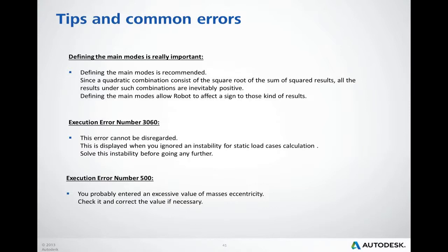Sometimes error 500 may appear. It's related to excessive value of mass eccentricities. In such case, it's recommended to check if the values of eccentricities are correctly defined.